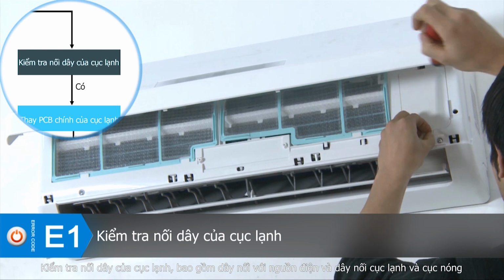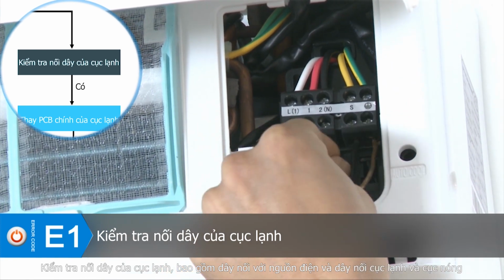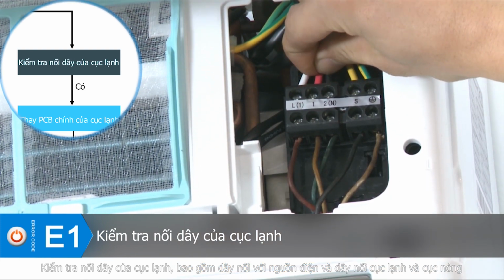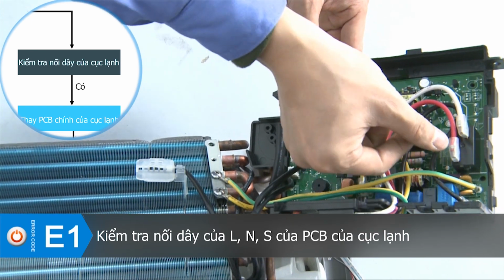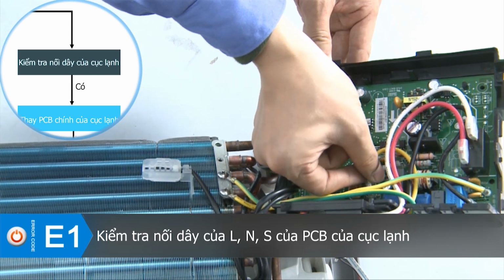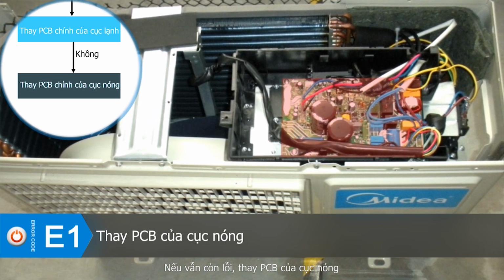Check the wiring of the indoor unit, which includes the power wires and the connecting wires between indoor and outdoor units. Check the wiring of L, N, S of the indoor PCB. If the error still exists after the maintenance above, replace the indoor PCB. If error still exists, replace the outdoor PCB.